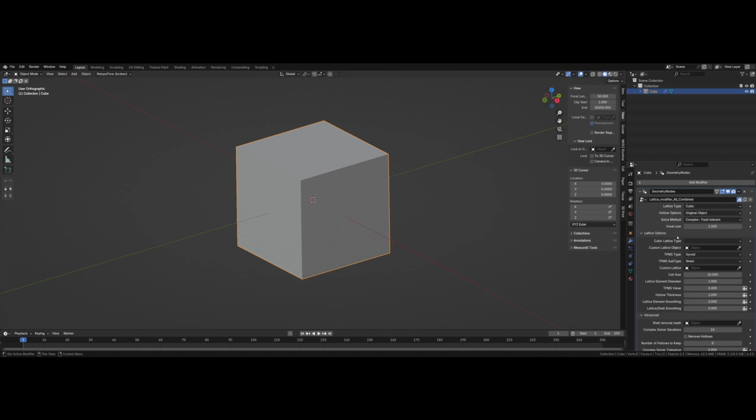Again, there are an intimidating number of options, but in reality the task you are likely to use it for only uses a few of them. Some things to keep in mind first. The units are dimensionless, so a value of 1 means one of whatever units you have Blender set up to. I mostly work in one Blender unit to 1mm scale and design the tool around that. Just keep it in mind if you need to do any conversions.